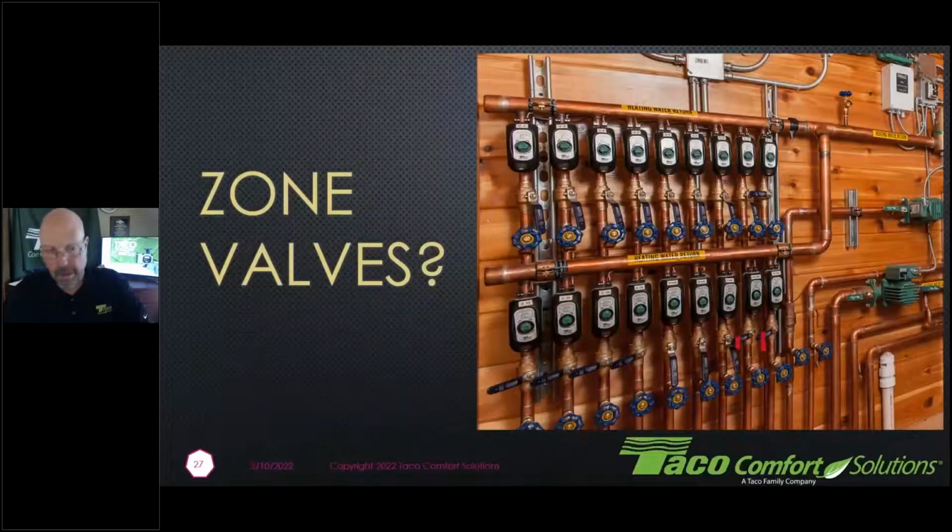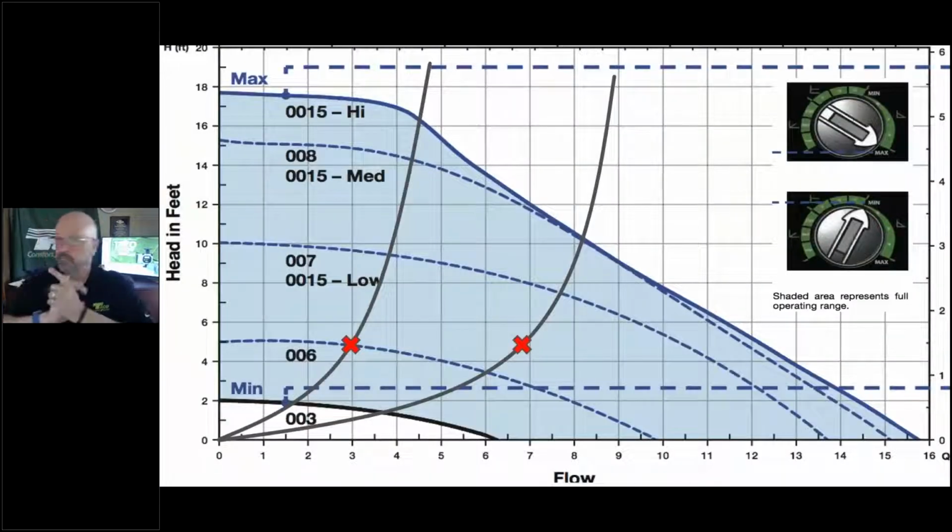Dave, we've had a lot of questions come in, just involving some applications. Will these work well with an existing heating system, hot water and radiant? And the answer there is yeah, absolutely. Any system where you're using a standard efficiency circulator, you can certainly apply an ECM circulator with similar, if not better, results, because you can dial in the speed that you're looking for, as you suggested. And again, especially with zone valves, it'll speed up and slow down as zone valves open and close, based on the constant pressure mode that you've selected.